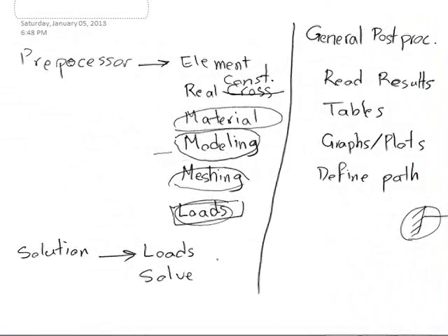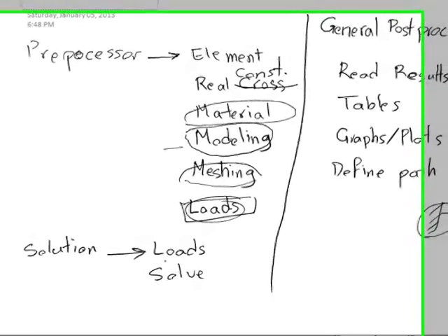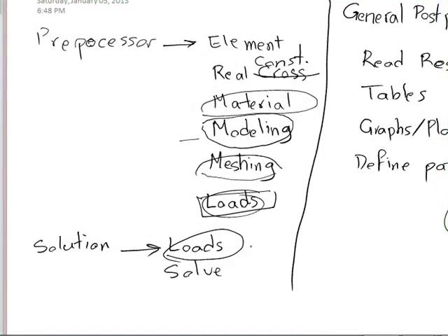And then, as I said, in the solution step in ANSYS, you can also define loads. This is basically the same thing. You can change loads in either of these two steps, the preprocessor step or the solution step. And there is the solve sub-step in the solution step, that when you go through there, you can start solving the model and analysis that you have just made in ANSYS.